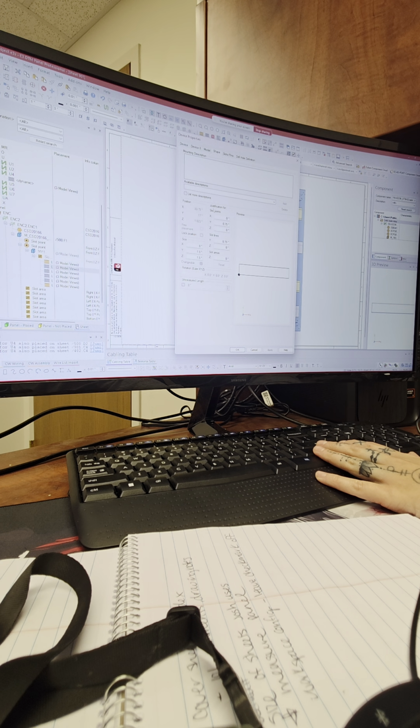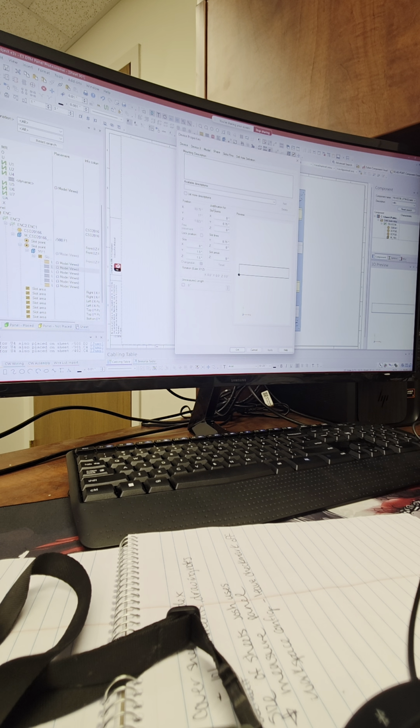Right click, device properties. So here on the left side, where you have your X, Y and Z size for that matter, Y being 1.5 inches, one just below that section, they're right there. So 1.5 is our current height and width of these ducts. Now, considering you're not using either the height or width of these, I would set them to be like 0.1, 0.1, both for height and width, because you really don't want any interference in your layout at all. From a duct perspective, you want them to be as least impactful as possible. While the length is okay, length can be 8 inches, that's all right.